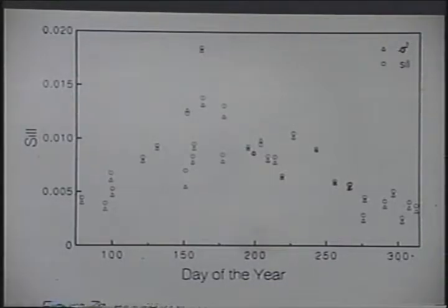in the case of a homogeneous random function, the structure function reaches a plateau beyond a certain value of the lag, namely the range. And this fact can be used as a tool to diagnose whether or not a surface is indeed statistically homogeneous.